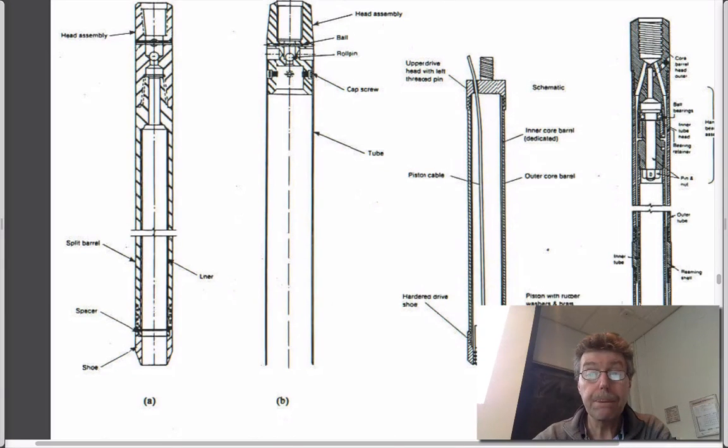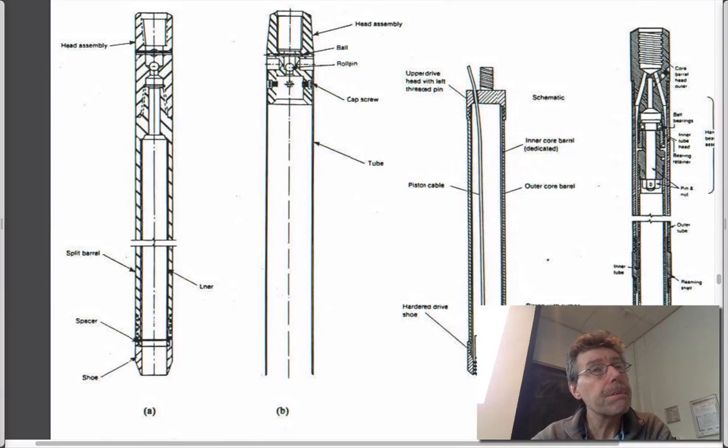Yeah? When they're drilling, if they're looking for a water table, how do they find the water table if they're using water to reduce friction? If you're drilling with air, you'll find water because it'll blow back as a mist once you get there. Then you know you've hit water. Water tables are often in the soil above it, but not always. So if you're augering, then water will rise inside the casing that you set, so you'd know that.